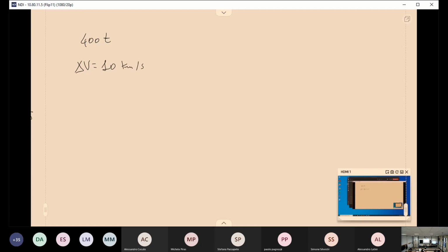And it includes similar stages, all characterized by epsilon equal to 0.12, so 12% of inert mass fraction, and specific impulse of 3,000 meters per second. So we will look for the minimum number of stages which is needed to get a payload greater than 4,500 kilograms.